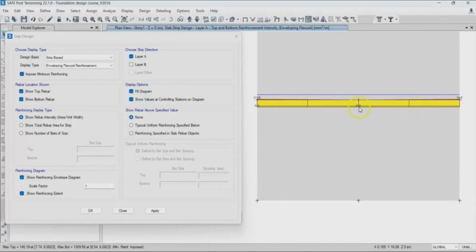So at this part, we are going to be having severe tension, like massive tension, because the column pushes down on the center of the footing, right? So at this part we're going to be having severe tension, which is at the bottom of the concrete. Okay, so take a look at this demand. So this is just showing the demand, right?